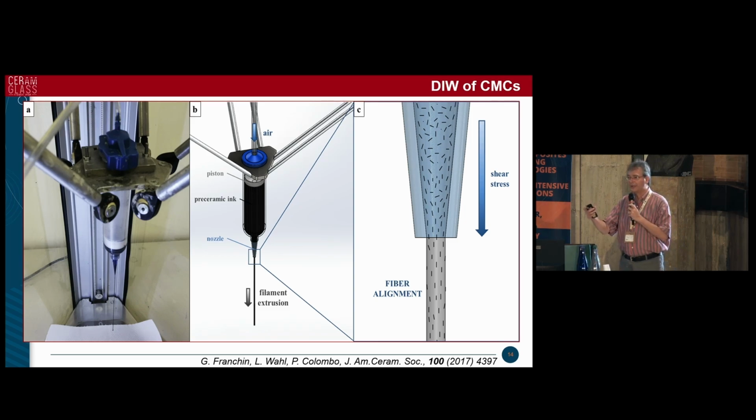because this means that after extrusion of your fluid, of your paste, you can retain the shape that you have just given, because after release of the shear stresses from the nozzle, the viscosity increases dramatically, and this helps keep the shape of the part.